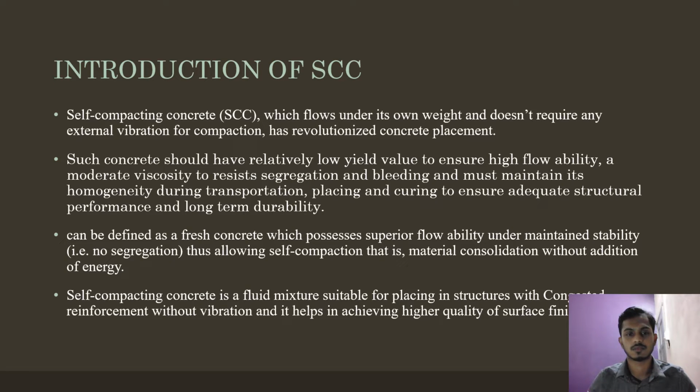Such concrete should have relatively low yield value to ensure high flowability, moderate viscosity to resist segregation and bleeding, and must maintain its homogeneity during transportation, placing and curing to ensure adequate structural performance and long-term durability. It can be defined as fresh concrete which possesses superior flowability while maintaining stability.